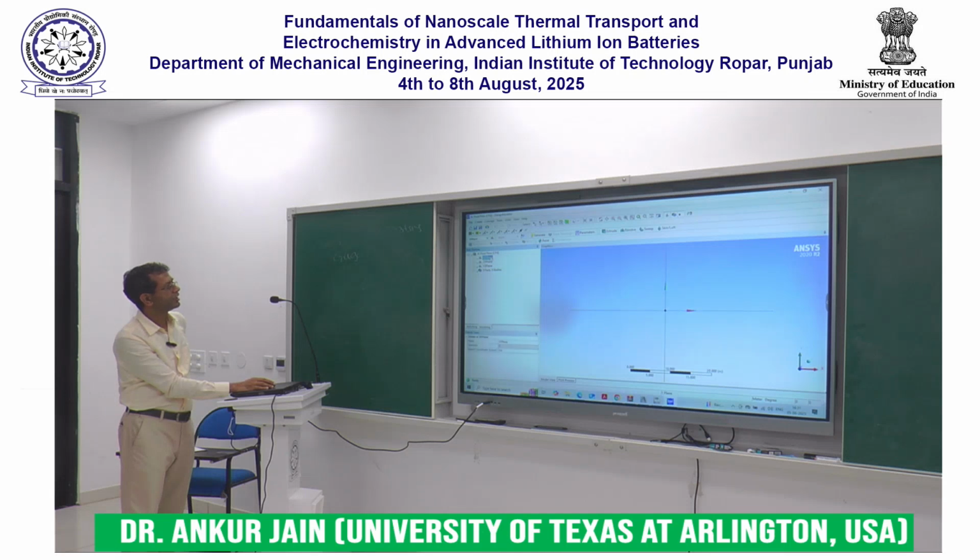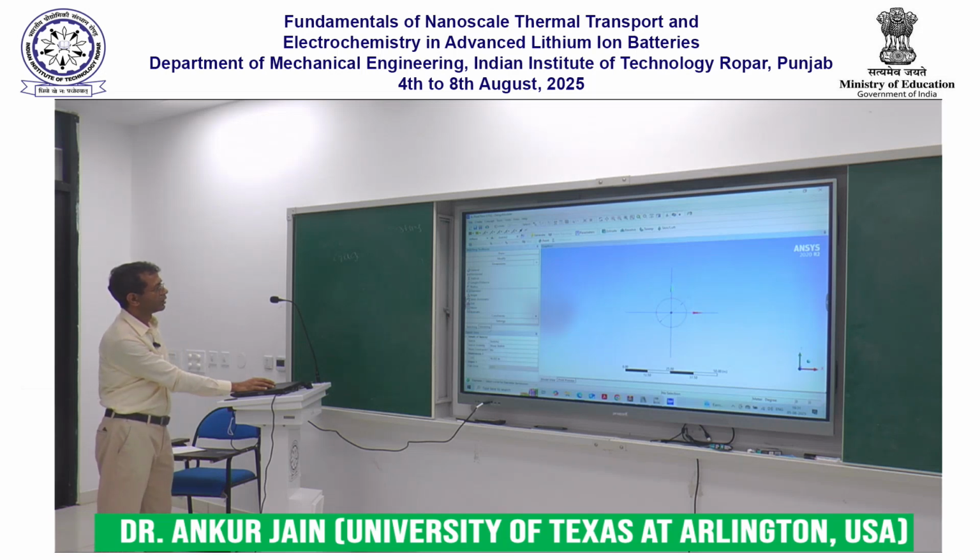So here is my XY plane. I will look at it. I will create a sketch, a circle, of whatever the radius may be. 16 is okay. And then I will create a new plane. Sorry, I will extrude this first. Sure, this looks good. So I've created my geometry.